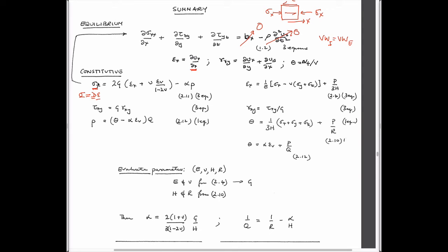Individually, it looks something like that. Sigma equals something times strains, but including pressures now. So this is a constitutive equation that's written in terms of effective stresses, total stresses, strains, and fluid pressures. And so we should be able to substitute it in for this value.